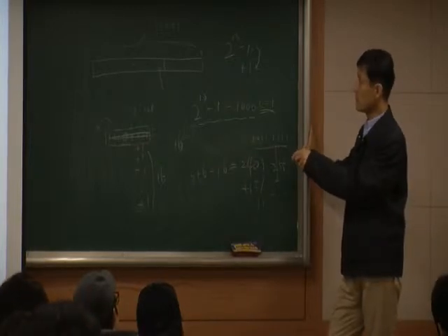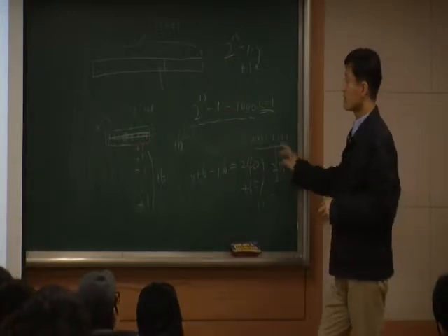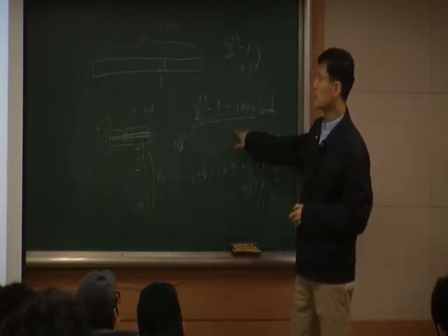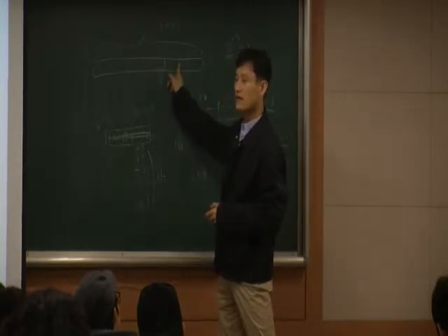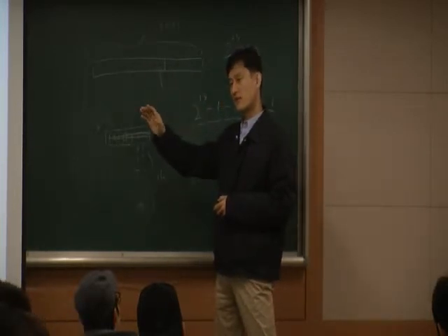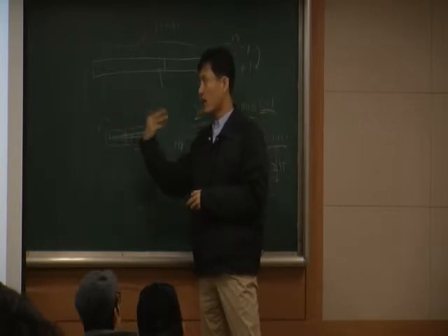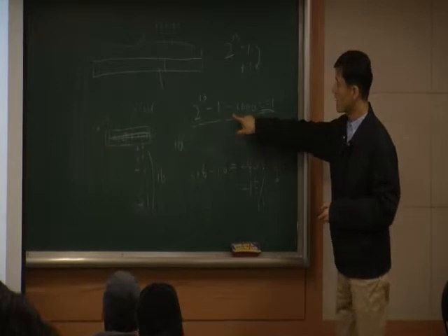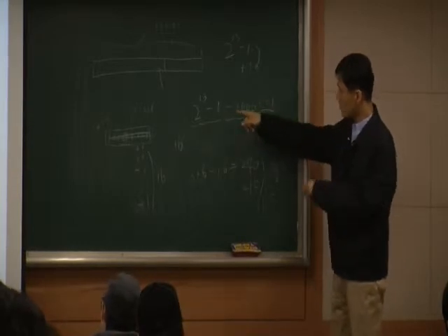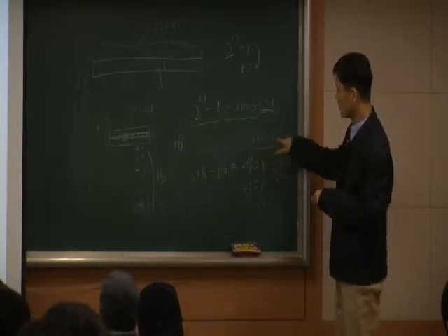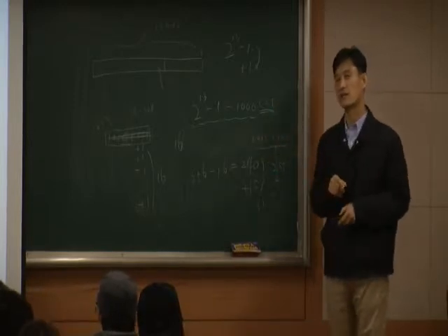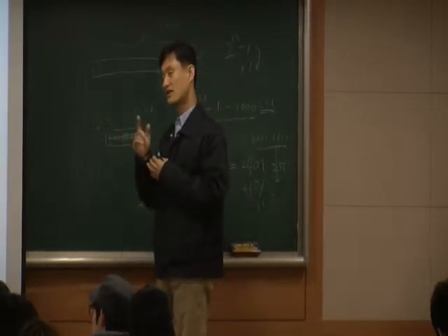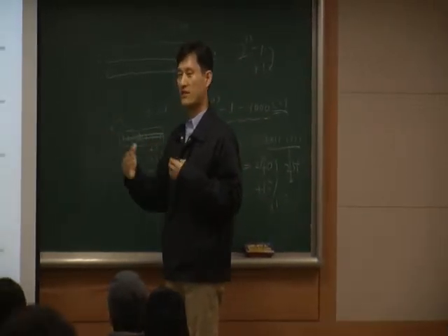Same thing here, right? If you want to count 1,000 pulses, then the maximum value minus 1,000 is the initial value you want to program here and run the timer. Okay? And then every time you have a pulse, this value will be incremented. And when you have 1,000 pulses coming in, now the remaining value here becomes all 0, and now we have a carry. That's the time that now you have 1,000 pulses. That's exactly the time of 1 millisecond of delay.